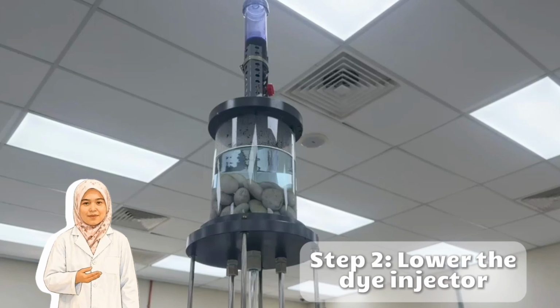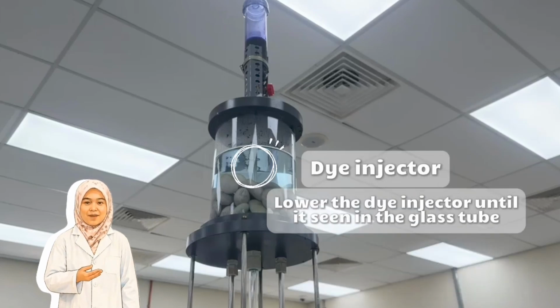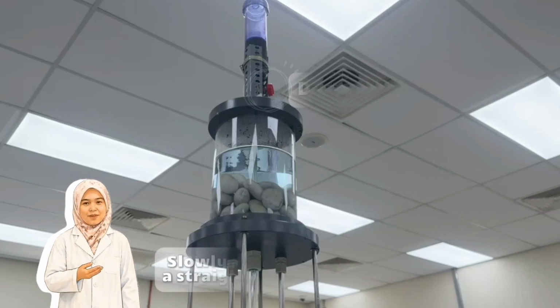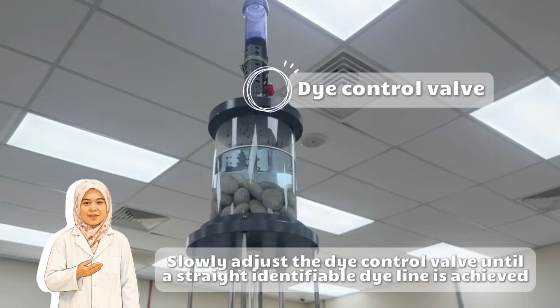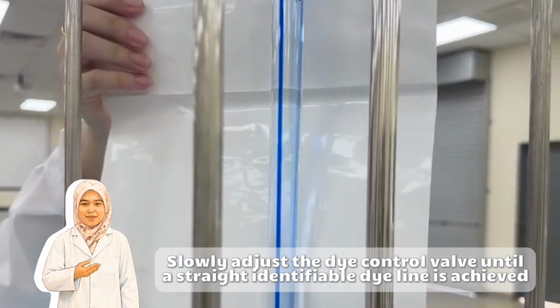For the second part, dye injection. As we can see, the Osborne Reynolds apparatus at the upper part has a dye injector. It was lowered until it was visible inside the glass observation tube, and then the dye control valve was slowly adjusted until a steady flow of dye injection was achieved.